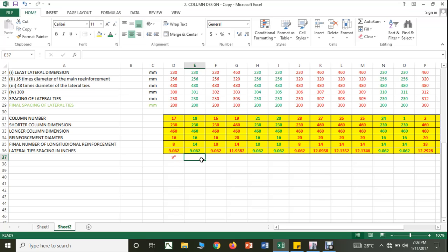If you have a very large project where tons and tons of steel is required, then you can get that exact diameter like 22 directly from the manufacturer, because you need it in large quantity. Otherwise, shops usually don't bring such diameters because they will not be fast-moving stock. That's why we usually go for 16, 20, 24, 28, 32, 36.